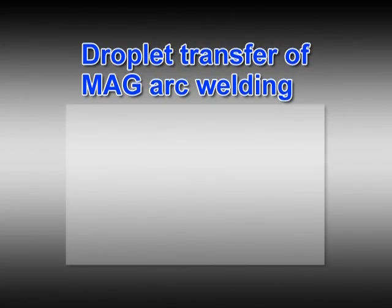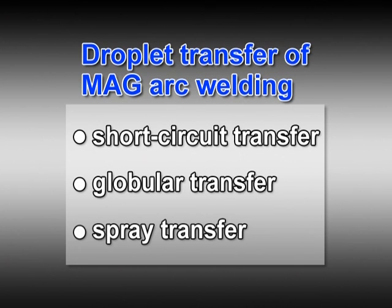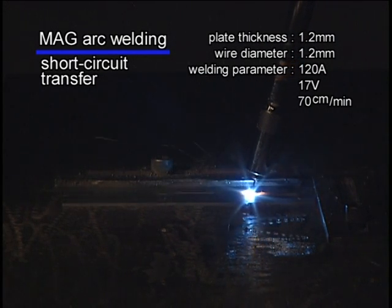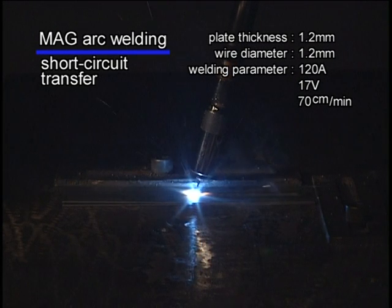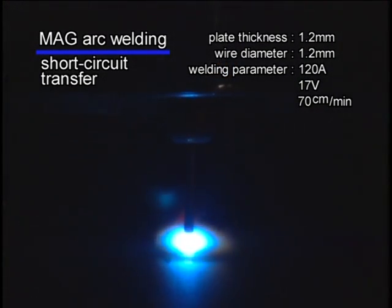In the MAG welding process, melted metal particle transfer is divided into three types: short circuit, globular, and spray transfer. First, we will observe short circuit transfer. This example shows a 1.2 millimeter thick plate using the MAG welding process. The welding parameters are 120 amps, 17 volts, and a travel speed of 70 centimeters per minute with a 1.2 millimeter diameter welding wire.